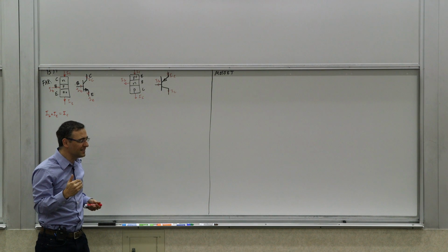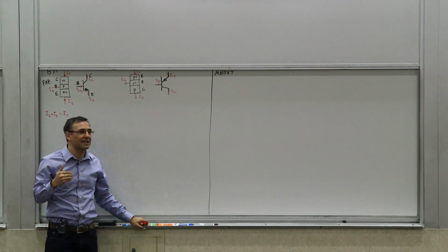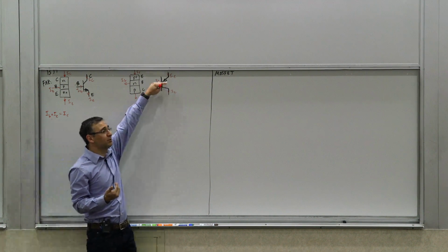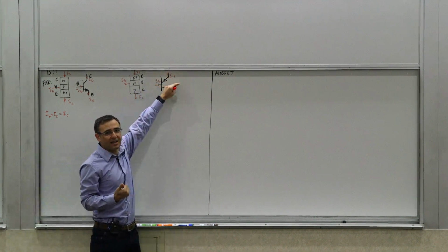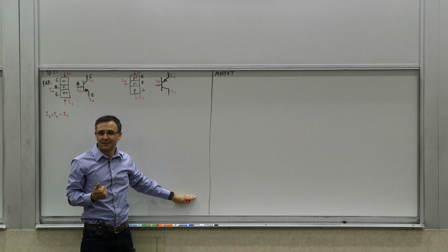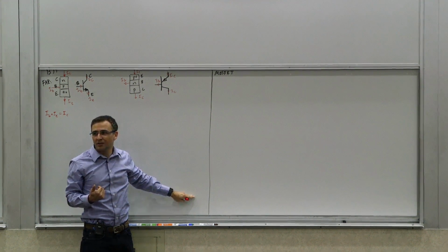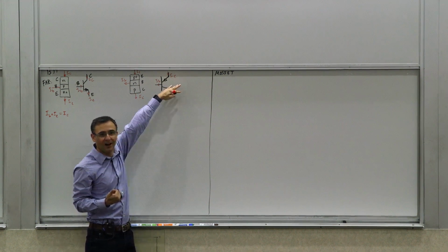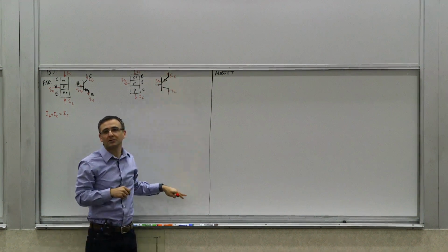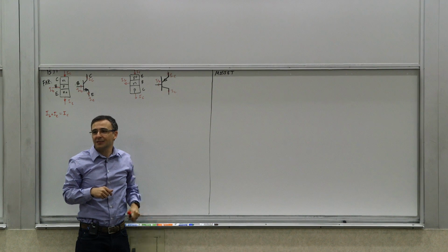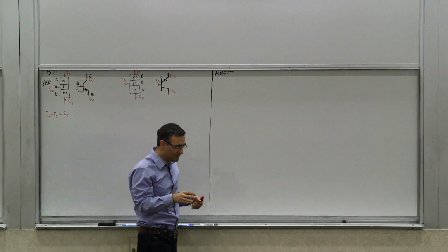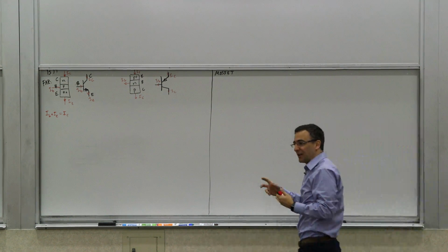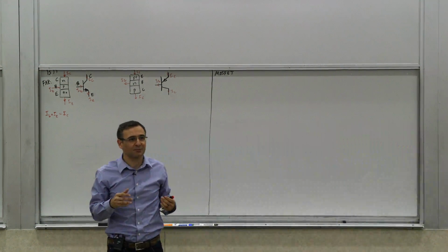So in that format, they are topologies, so it doesn't matter. But there's something that makes understanding and designing and reading circuits a lot easier, which is trying to keep the higher potential higher on the schematic and lower potentials lower. So if I'm drawing a circuit on the whiteboard, the higher potentials would be drawn at the higher points, the higher elevations, and lower potential will be drawn at the lower elevation. And you can draw the same circuit many different ways, and I can take the same circuit and make it very complicated, very difficult to understand.